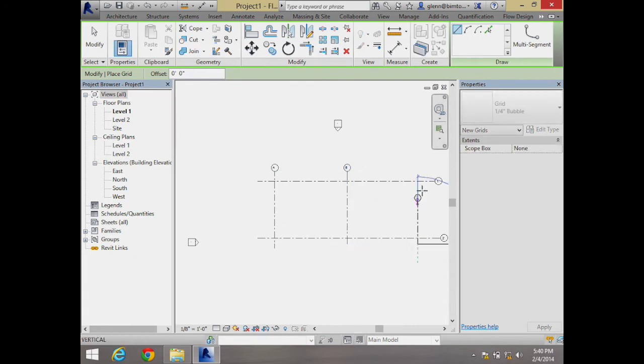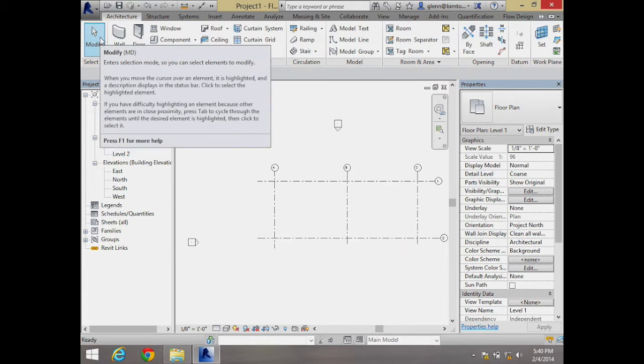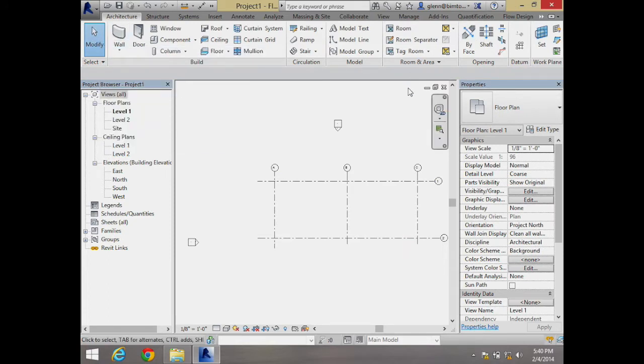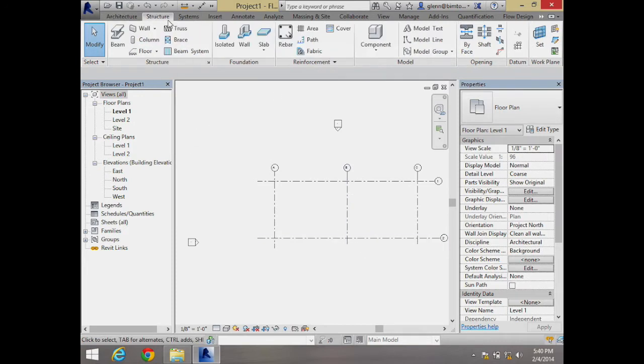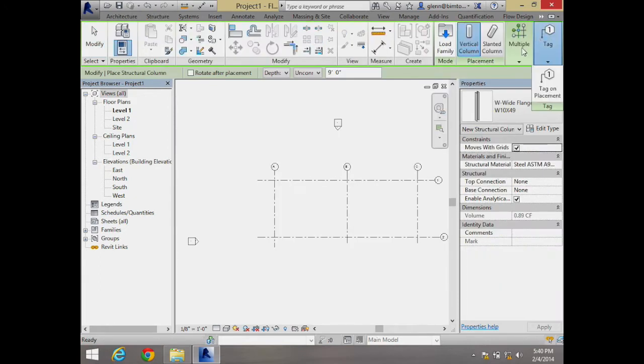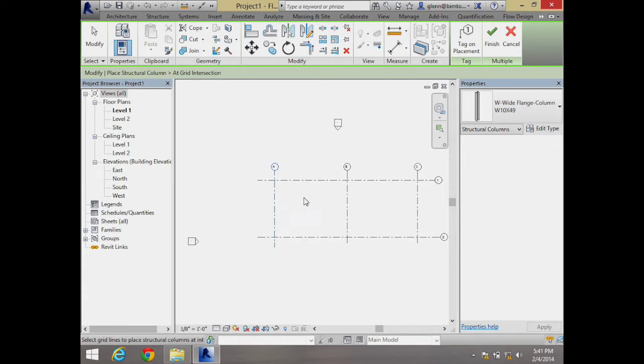Now, in terms of thinking about this floor we're going to put in here and having to support that floor, I can put the columns on this first level. That's going to work out just fine if I want to put them at those locations. So I'll put some structural columns in. I can choose the type of column. Since on level 2, I'm going to go in height instead of going depth, I'll put them up to level 2, and I'll just let them be those steel columns. Let me say it's going to be those multiple columns. I'll just put them at those grids. Here, here, and here. I'm selecting those grids in the opposite direction. So now I should have 6 of them at those different intersections. Okay, hopefully that's looking pretty good.